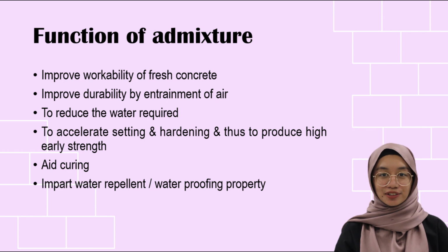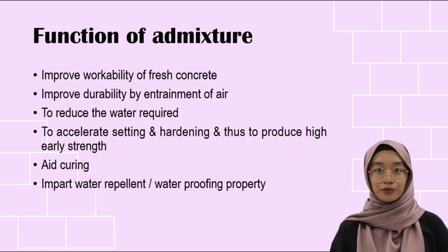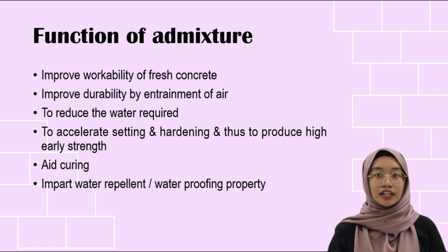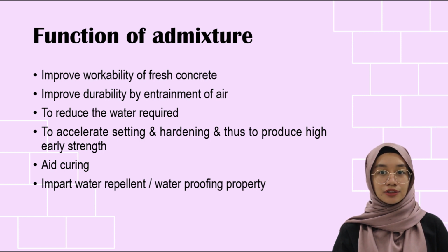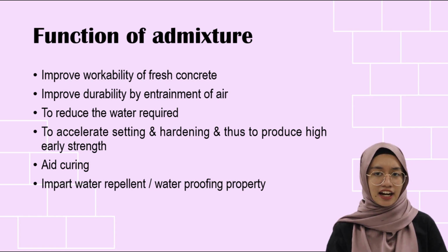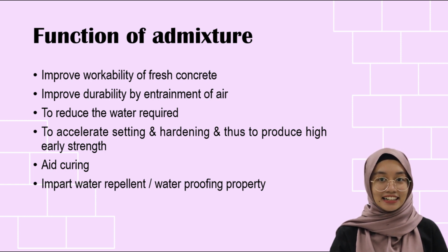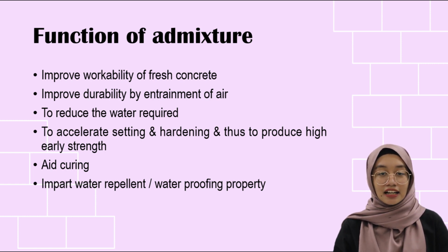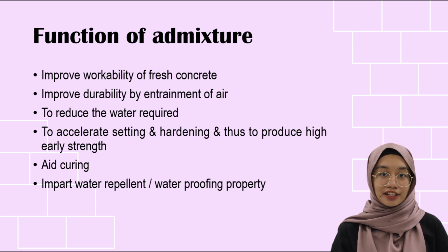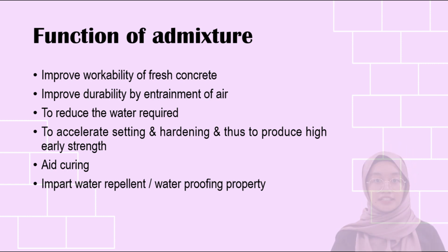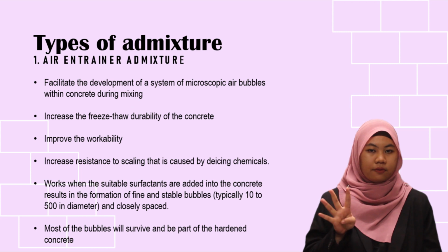Function of admixtures: to improve the workability of fresh concrete, to improve durability by entrainment of air, to reduce the water requirement, to accelerate setting and hardening and thus produce high early strength, to aid curing, and last is to impart water repellent or waterproofing properties. There are 4 types of admixtures.